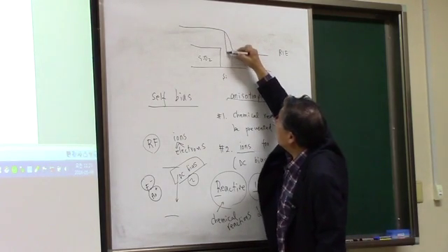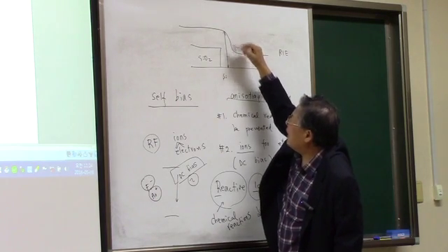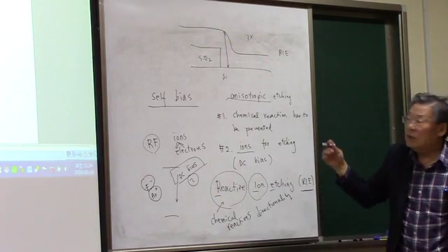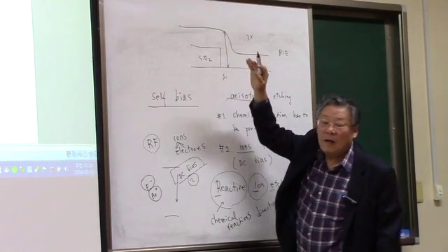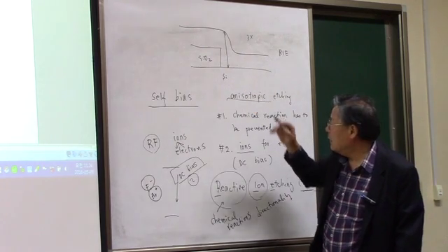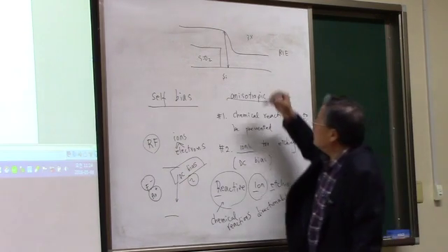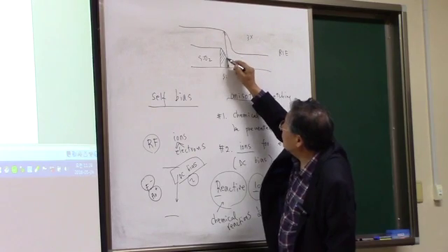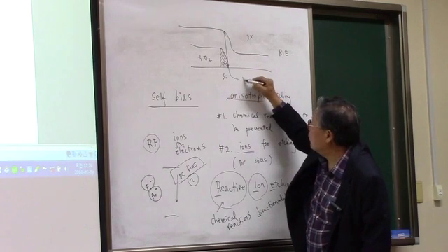So when you look at the side wall, the height to be etched is going to be about 3 times thicker than the other part, so that if you do the etching, here the anisotropic etching again, not with the wet etching, then because of the directionality, you're going to have some materials left along the side wall of the SiO2, and we call this residue.